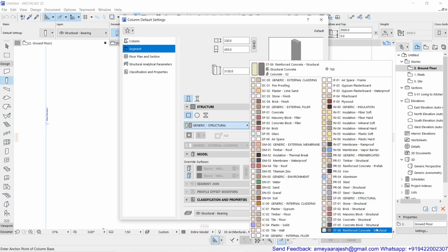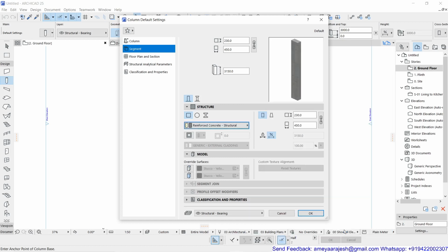If I stay on this, at the top you can see there is a 760 as the number for its strength, which we can talk about. That value is going to determine how this material is stronger compared to others. For example, last time we have taken the brick, which was 540 at the top, and this reinforced concrete is 760. So this is going to be much stronger than brick. How it will affect, I'll show you on screen, but just select this.